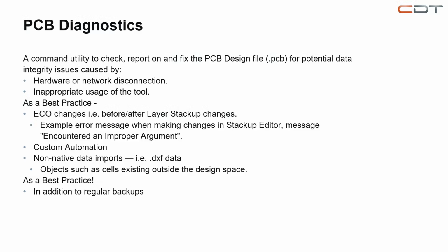As a best practice, you need to check your PCB once you have stack-up changes, or once you have some specific errors, if you used custom automation scripts, or if you imported something like a board outline from DXF, because it will be imported as a cell. So do it from time to time, in addition to regular backups. About backups a little bit later.